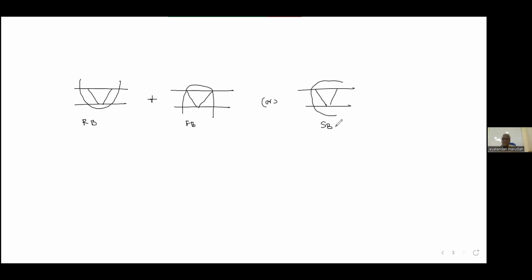Is it clear? Now, which bend is required? For procedure qualification also, the bend test is mandatory. A welder also we can qualify using a bend test. It depends on the thickness. For thickness less than 10 mm, so 10 millimeter in the code language is 3/8 inch, for PQR we have to do only two root bends plus two face bends.